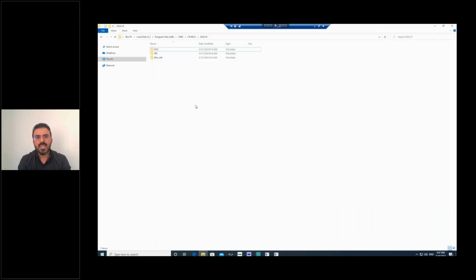It is worth mentioning that the controller comes with documentation in which you will have quick start steps and the workflow of how to use the controller and do the coupling process. We also provide a number of examples in the template folder. In each folder, you will see a separate LedaFlow model and GEM model that you can couple together and explore. That is achievable by using the latest commercial releases of GEM and LedaFlow for the coupling process.